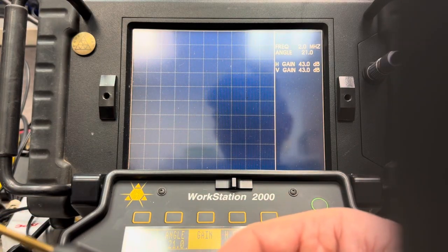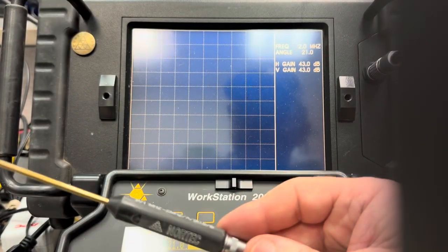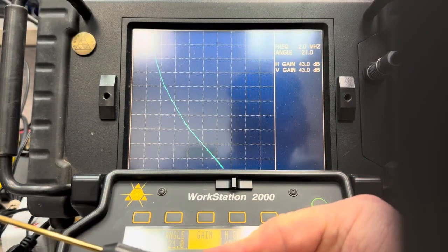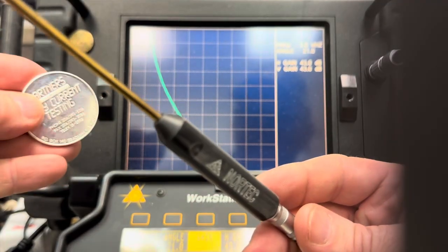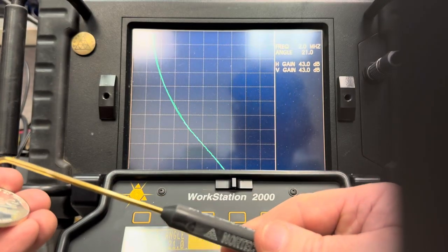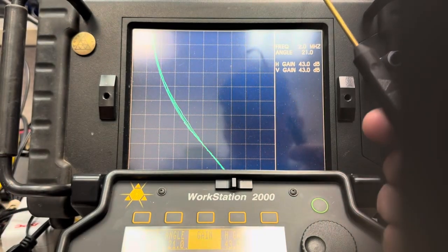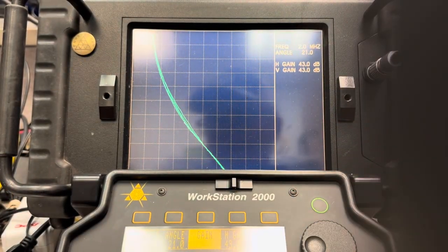Let's try that again. What if I wanted to separate copper, of which I just happen to have a bar here and a thicker sample? Let's try the thick sample of copper. Look at that vector. Now let's look at the 99.9% pure silver coin. They're both like 100% or 101 IACS, right? You can't distinguish the two. So obviously high frequencies do not work for separating two high conductivity materials.